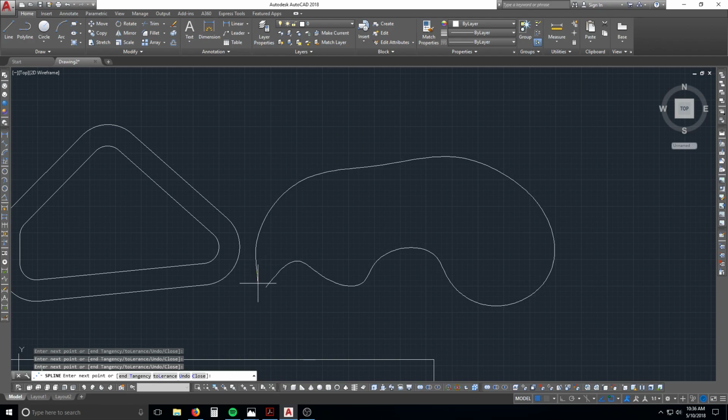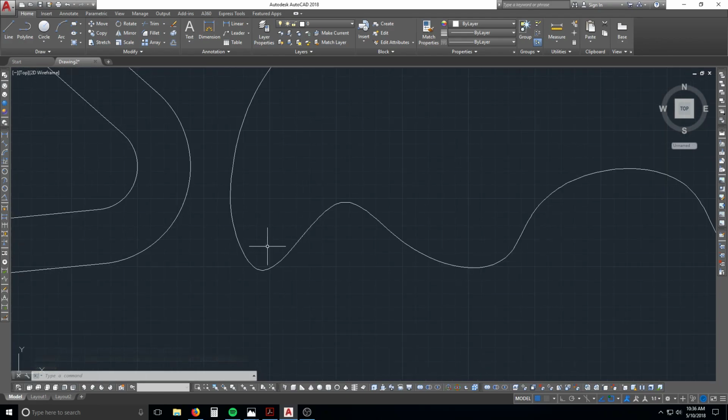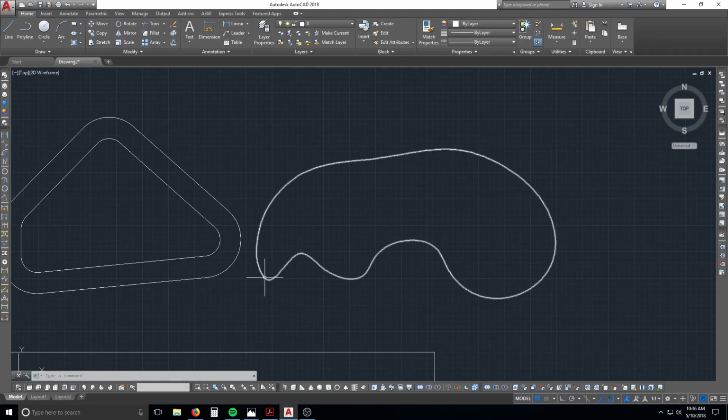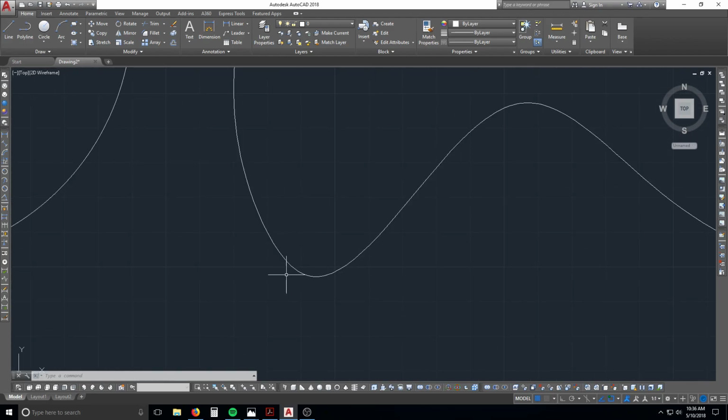And you get over here and type in C, enter. C was for close. You're closing the gap. You're asking the computer, hey, please think for me here. I'm pretty close to where I want to be, so just close it. Because a lot of times when you're using spline, if you close it, it'll give you this loop on the side, and I'll show you what I mean.